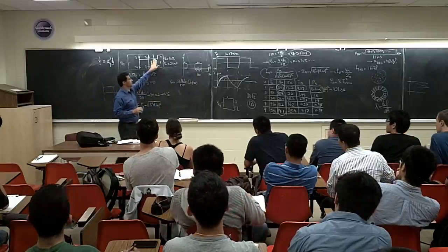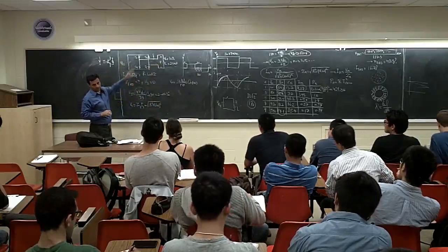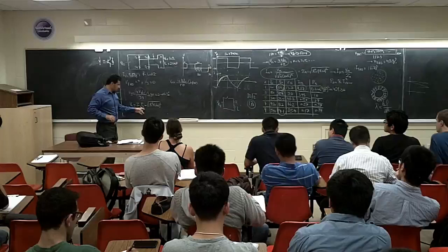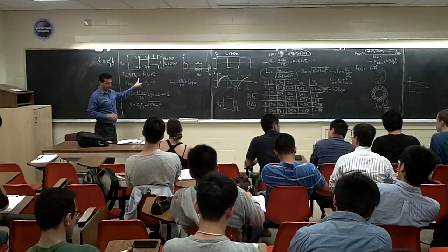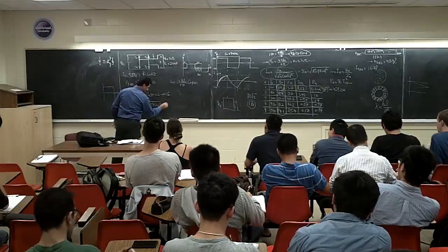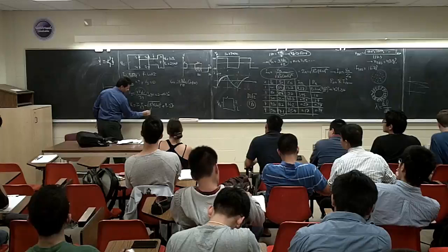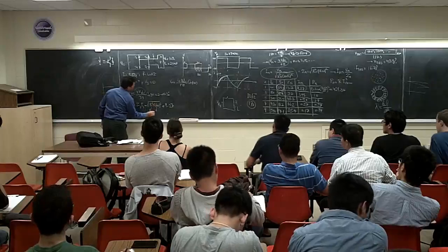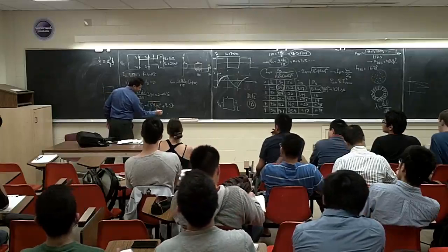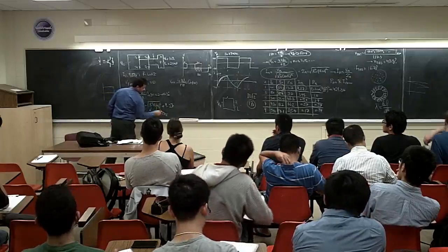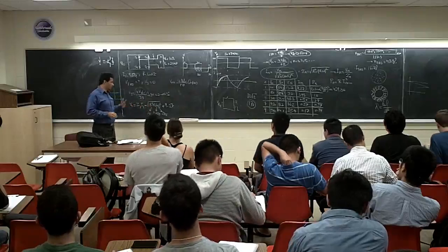No, there's no capacitor. I said if you want to clean up the voltage, you put the capacitor there. So how much is I1? I have it here. How much is R? It is 10 ohm. How much is L? 0.025. How much is omega? 377. You put all these numbers here, so you can calculate your V1.